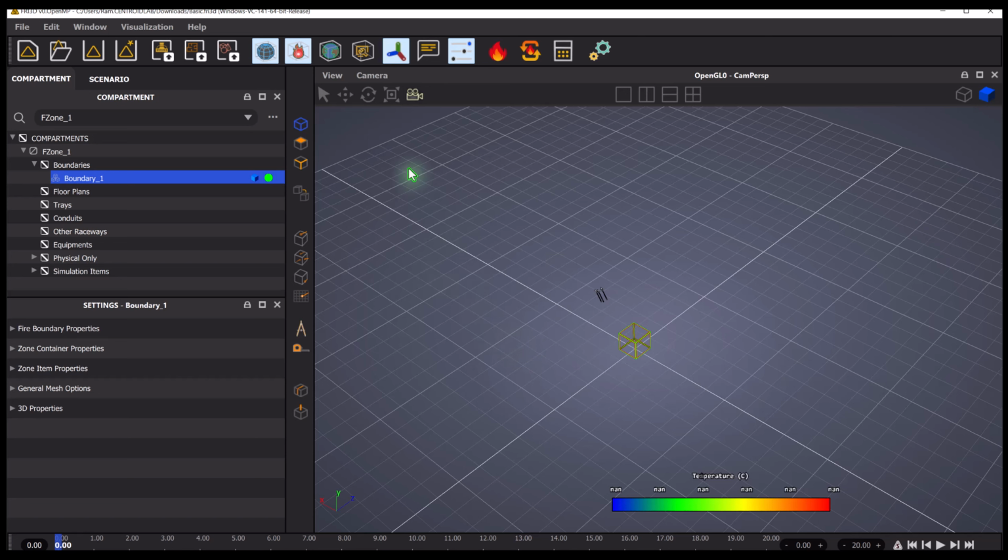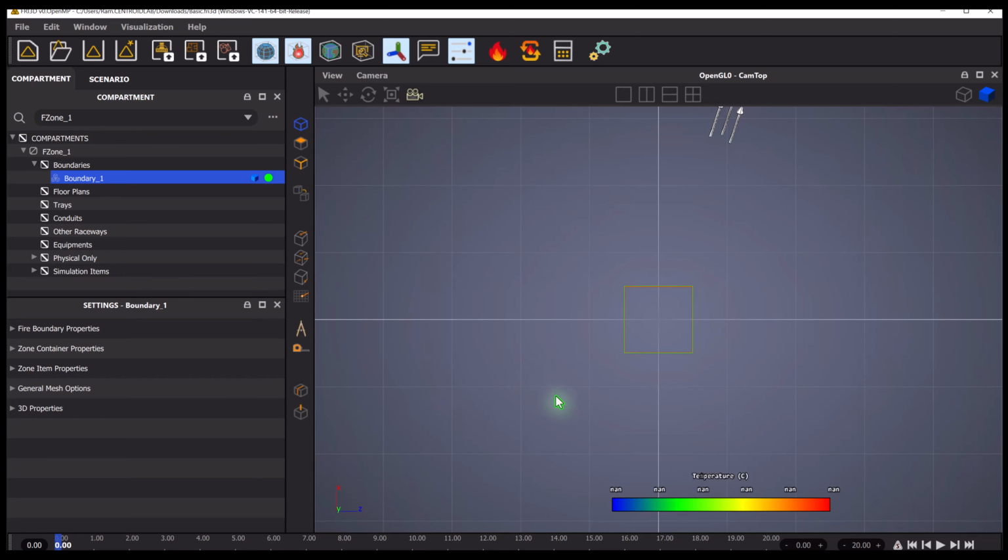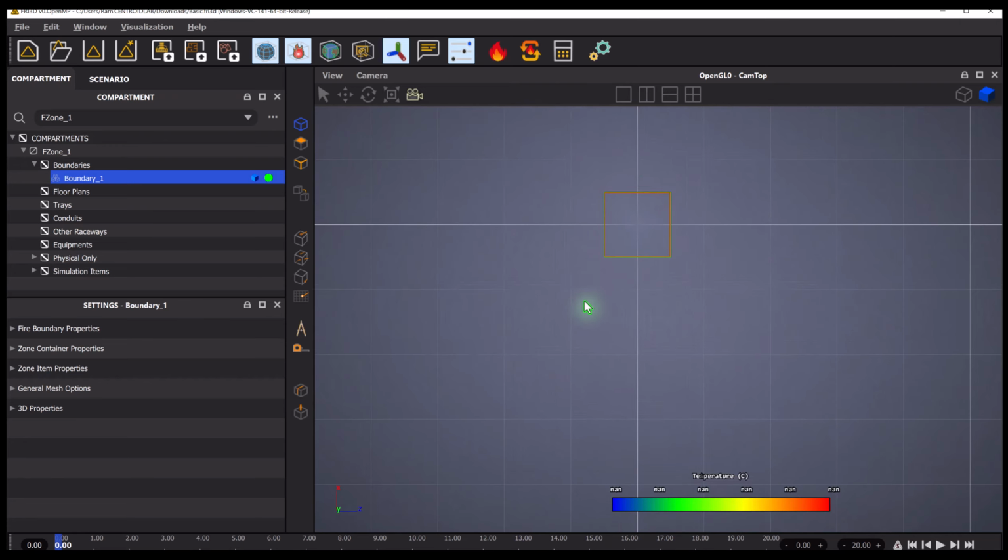And for that, we can go here just to make sure it's on the positive side of things. You click on the camera and you select the top view. What that does is reset your view to the top. Here are the manipulators to use in your 3D window. Alt button and right mouse click goes up and down, zooms in and out. Alt and middle mouse button pans the camera.